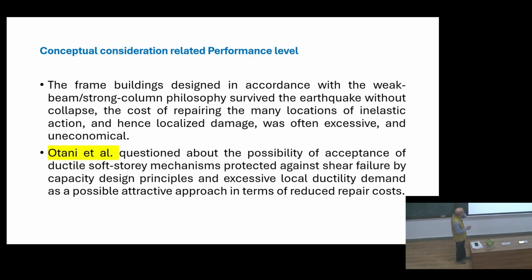In design, even with this concept of weak beam, strong column, the structure may survive the earthquake, but if it goes into inelastic deformation, sometimes it needs excessive repair or retrofitting.